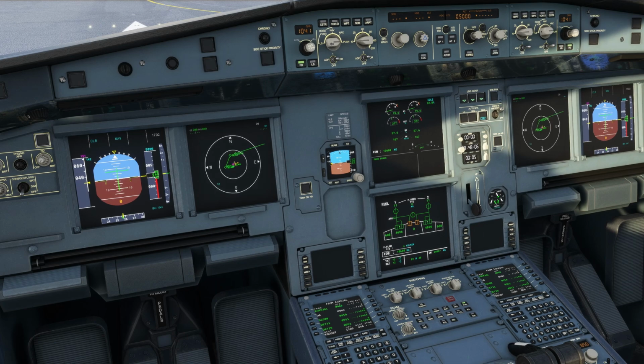If I turn it all the way to the right to plan, I'm now able to check my flight plan and step through the various legs by clicking on the up arrow key. And I'm doing this just to check that my flight plan is as expected. Normally, of course, you would do this before getting on the runway. And as you step through the various legs of the flight plan, you can of course use the rangefinder to zoom in and out so you can see more or less detail.